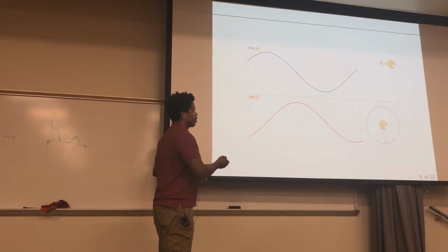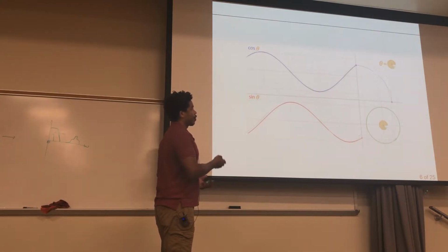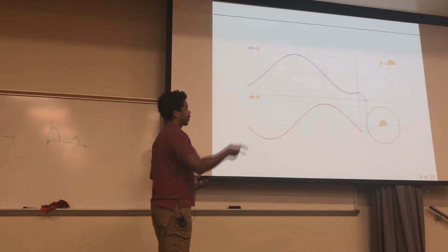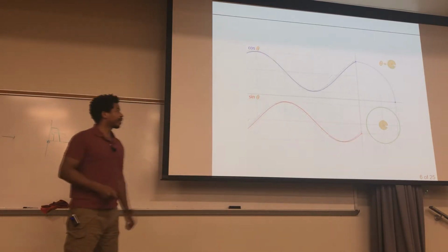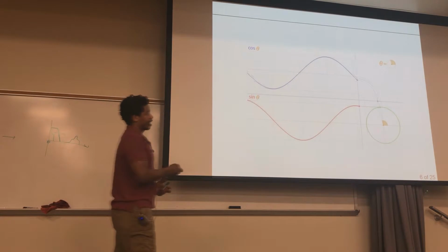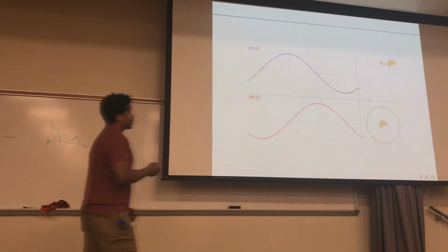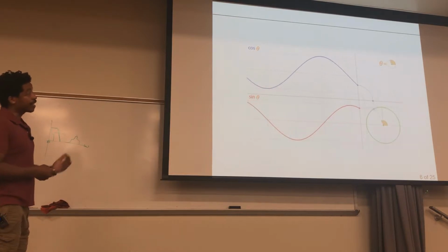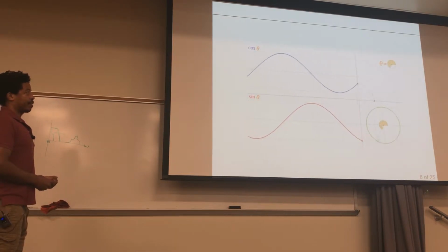So this is the magnitude going around, and right here the magnitude is 1. But your omega t is the angle that's being traced out. And so it's always going around like this, right? And you're taking a snapshot and looking at the phase. But as you can see, that comprises a sinusoid. And mathematically, it's really easy to deal with and think about.